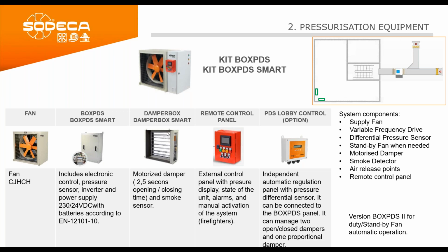It also has this damper box, a motorized damper with a fast response actuator, with just 2.5 seconds opening and closing, and it has a built-in smoke sensor. This is for the air intake. It also has an external control panel with a pressure display, a state of the unit, alarms, and manual activation of the system. This is intended for maintenance and for the use of firefighters.